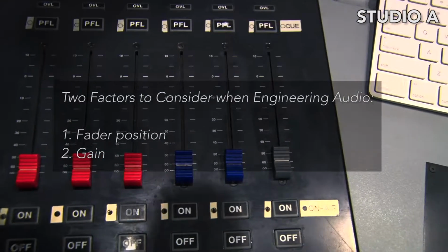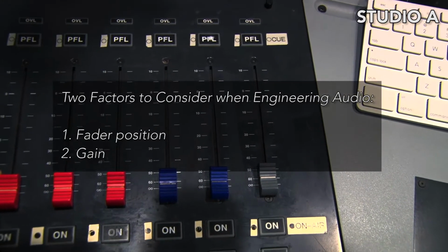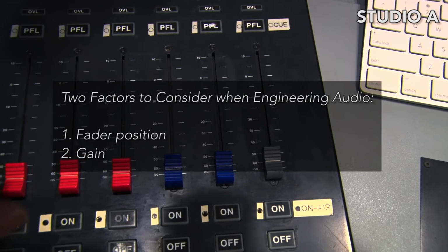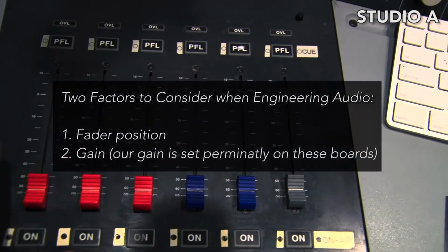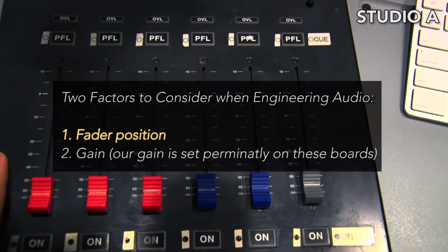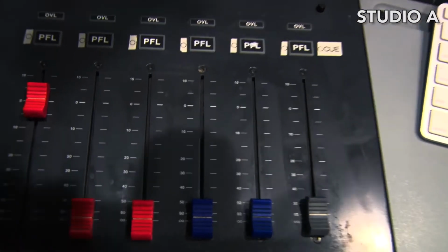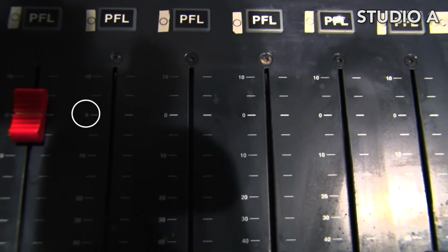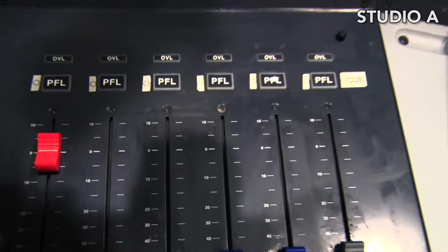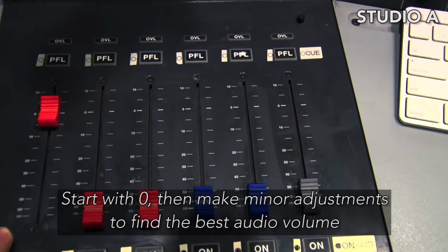When engineering audio in these studios, or really any console, there are 2 factors to consider. One is the fader position and the other is gain. And our gain is set permanently on these boards. So really, for this situation, you only have to worry about the fader position. It's best to always put your fader up to 0. You'll kind of see the 0 mark here. And you can see it's plus 10 above it and negative 10 below it. That's in reference to dB. So put it up to 0 and try out your audio best there.